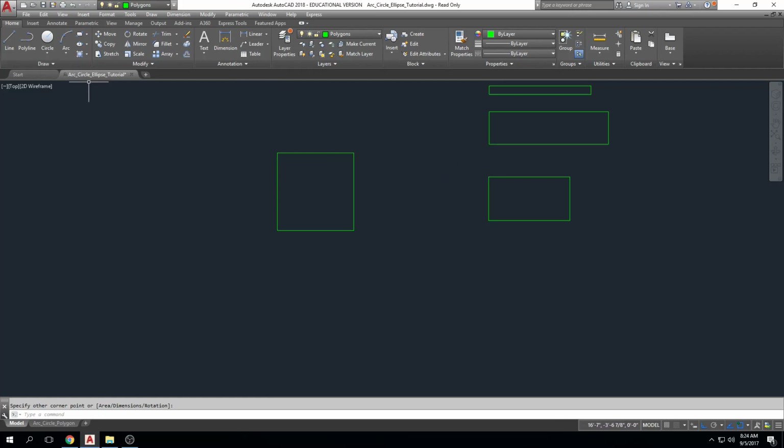Another way that I can create a dimensional rectangle is using relative input. I can come up here to my rectangle and click to initiate my first point. Since I've specified my first point using a click, that's already defined. Now to create my second point, I can either come down here to dimension and click, or a third option would be to specify an XY distance from that first point, a relative input. So I could type @6,6, enter. And that second point, the top right corner of that rectangle, is over 6 inches and up 6 inches from the beginning point.